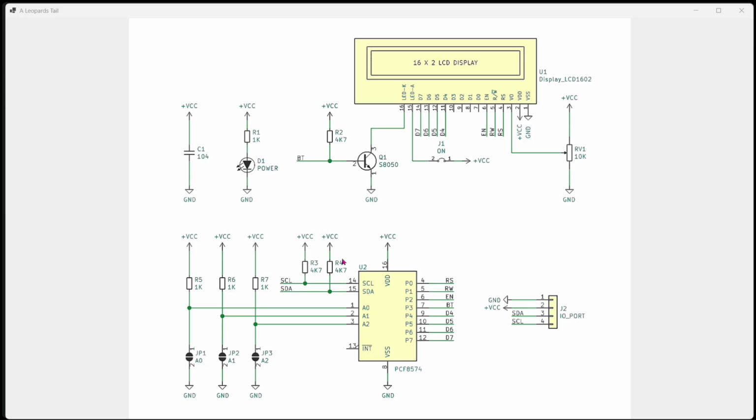And what I'm looking for is this. This thing has got two pull-up resistors. SDA and SCL need pull-up resistors. Slight aside, you don't want too many pull-up resistors either. So if you plug a load of displays in, you may find it stops working. It's not too bad. And try it before you start trying to desolder anything. But anyway, that's what we've got.